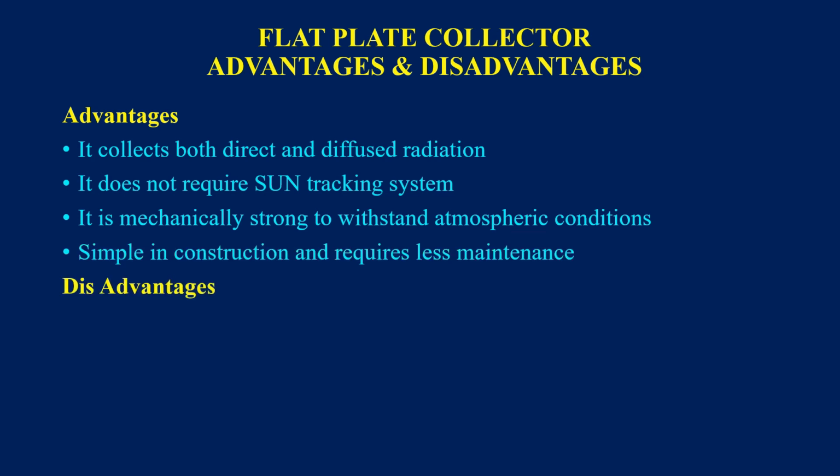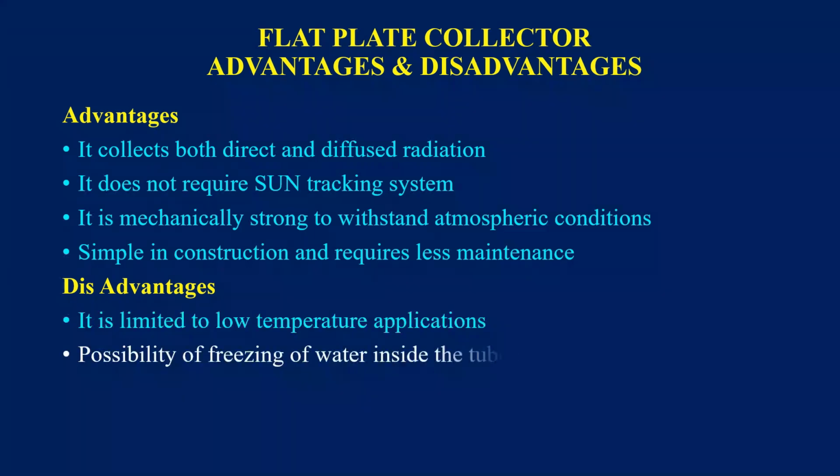Now coming to the disadvantages. The first one, it is limited to low temperature applications such as household water heating. The second one, possibility of freezing of water inside the tubes. We know that water is the most effective heat transfer fluid. If we are using water as a heat transfer fluid, there is a chance for this water to freeze during cold climates, and there is a chance to damage the tubes.